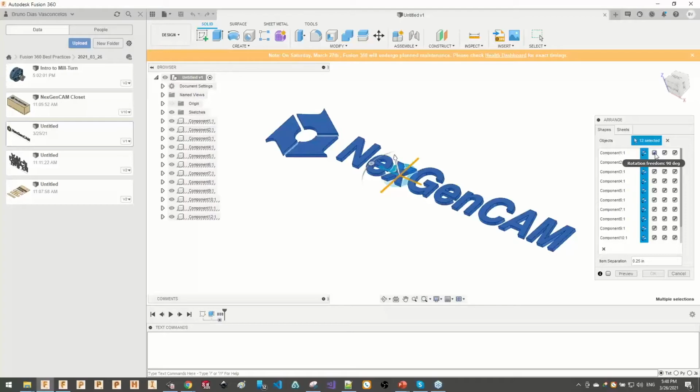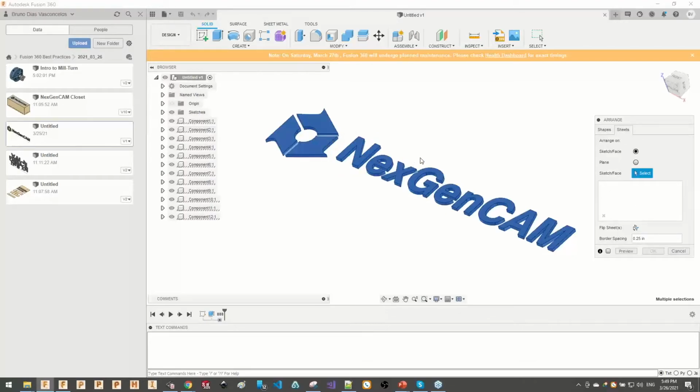So are you letting this rotate 90 degrees, 180 or 270? Yes or no? This is what these check marks are for. I'm going to let this part rotate only 180, not 90 or 270. This is going to improve the calculation a little bit, because I want to run this faster for training purposes. Here, item separation is the distance between each item. Under sheet is where you define the size of the sheet of metal or sheet of wood that you're looking to use.